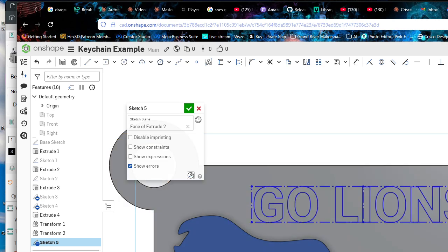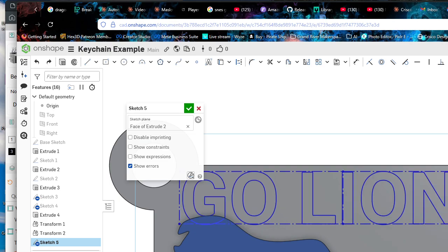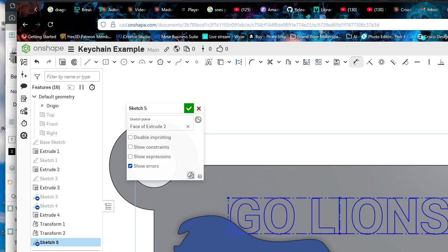Can you resize it after you draw the box? Yeah. How do you do that? So if you just have a blue box, and you already have the text in it, all you have to do is dimension, D on the keyboard. Pick the height of your text, and it will add a dimension to it. So then you could just change that. Like mine, it shows 0.58. Obviously, it's a little too big for where I want it. I'm going to do 0.4, and it should auto update.